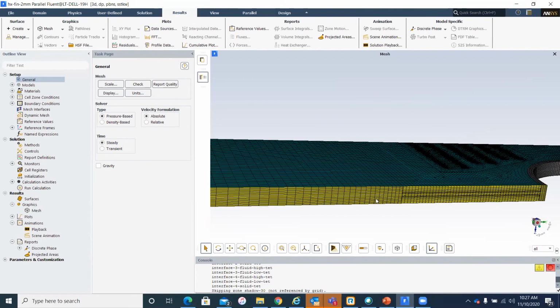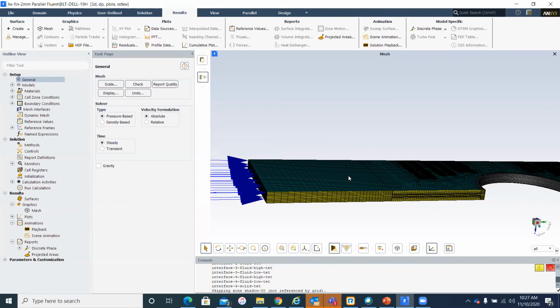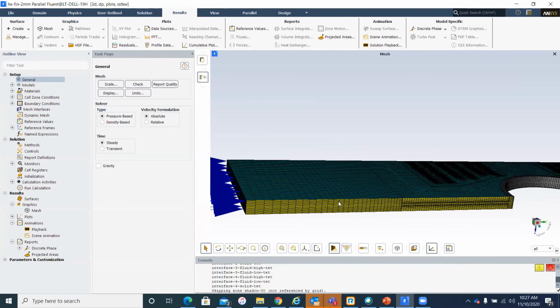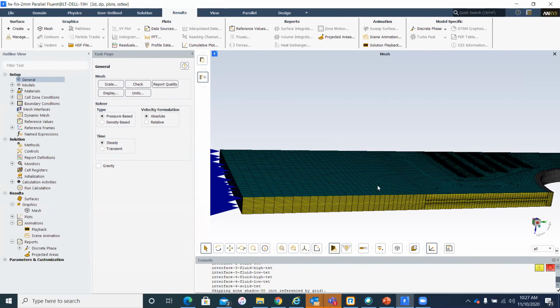What is a symmetry boundary condition? A condition through which there are no fluxes. So there is nothing going in or out. And we can do that because along a symmetry face, you can just create a mirror image of the domain that you're simulating. So about this space, I can just repeat the breadth of this geometry. It acts like a mirror face, right? So nothing is coming in, nothing is going out.